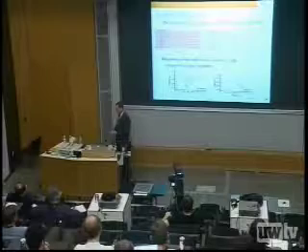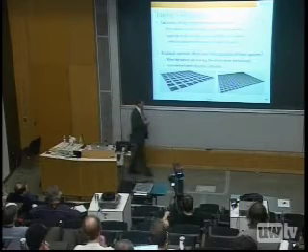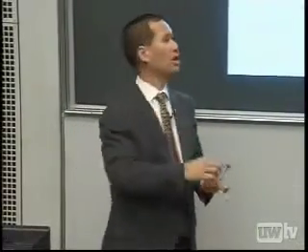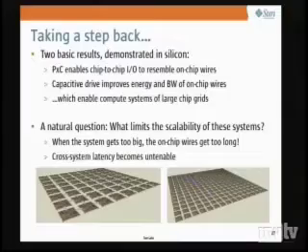Okay, so the notion really is that, take a step back. What have we talked about? We've talked about proximity communication that lets us have multiple chips tied together, in which the off-chip I/O is now made by on-chip wires. Number 2 is we made on-chip wires significantly better by using capacitors to drive the long RC interconnect for those long chip wires. So I can think of that as going hand in hand and enabling large compute systems of many, many chips tiled out. Okay, so the natural question is, what's the limit?